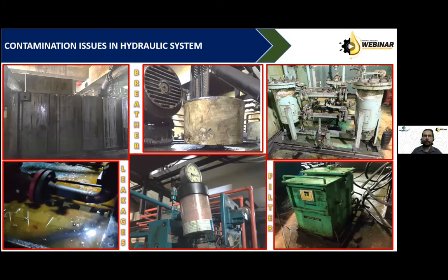So we have seen that for a bigger tank, a few machines are installed with model numbers having four digits, five digits. So it is a misconception that a model number like 1000 or 1500 shows that the system is capable of handling a large volume of oil. No, that is just a number, or maybe for some specific reason they have given the large number. For any purification system, we should check the flow rate of the pump. That will give the true picture of the flow rate.